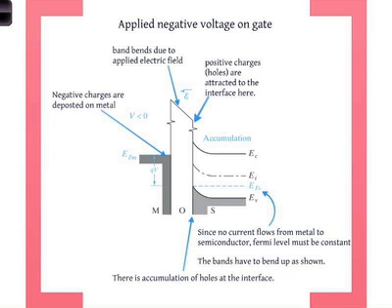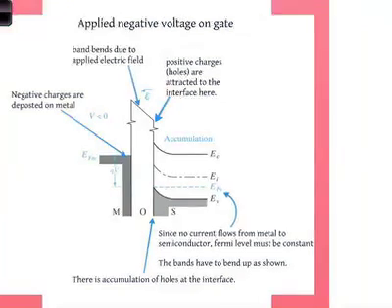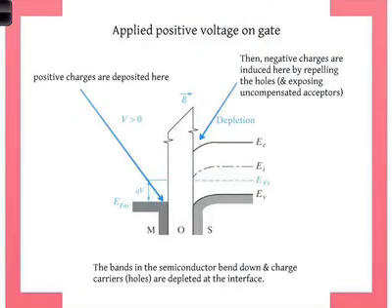Increasing the negative gate voltage increases the hole concentration, but the current really doesn't change very much because you already have lots of holes. The change in the hole concentration is small. So you have no control essentially. Okay? This is similar to forward biasing the JFET, if you recall. I had asked you about that. Okay? Now, applied positive voltage on the gate gives you the right condition.